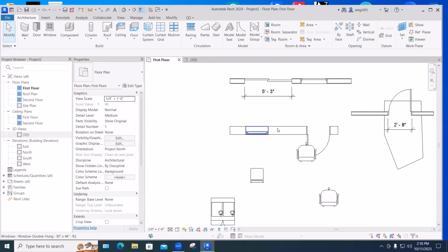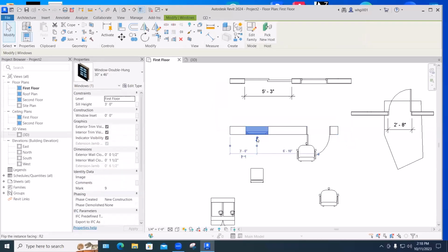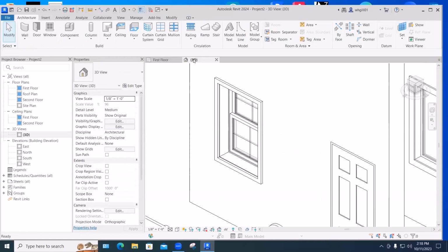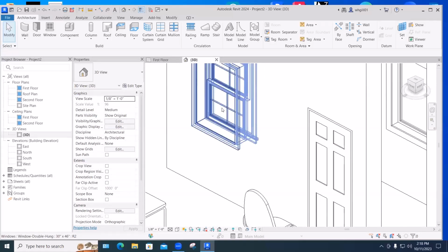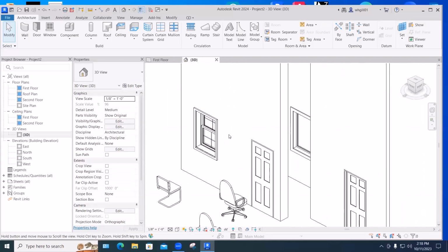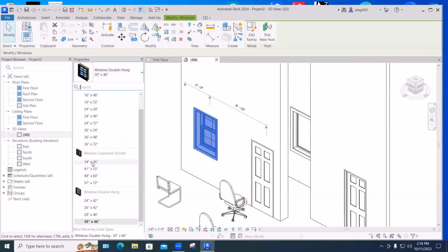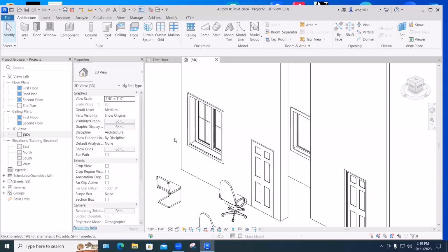So since this is the outside face of the wall, I'll pick the window and then hit the flipper arrows to make its outside correspond with the wall's outside. So if this is the inside of the wall where the furniture and the casework is, the window is pushed out to the outside, flush there, and that goes up and down. And we can just easily change that to a casement. That's the kind that cranks out.